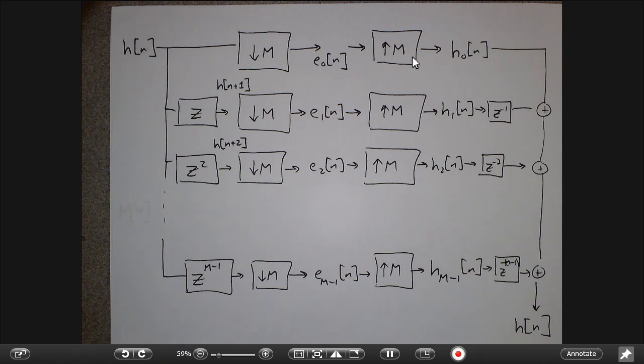samples here, right? It's just basically taking those little M strings and writing them. So in theory, if I had 30 elements here, and I would downsample by a factor of 3 in these blocks, I would have 3 length 10 subsequences, right? And this part over here tells me how to put those subsequences back together to obtain my original signal, right? I expand them by putting the zeros in, I shift them so that they're in the right place, and then I add them up, okay?